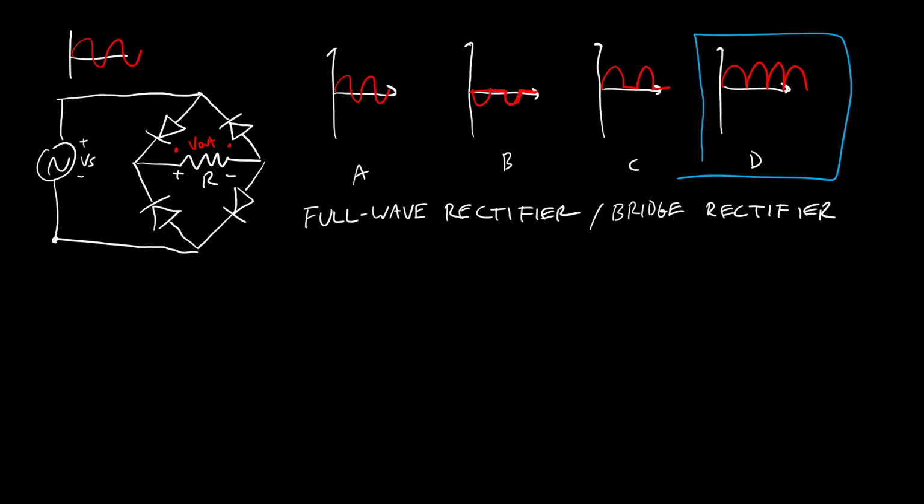Let's do something I should have defined earlier. I'm going to define ground there, just so we have a reference for 0 volts. And remember that with an AC voltage source, that means that's my 0 here. So this side of the source can swing either positive or negative relative to ground, depending on which part of this cycle I'm in. So when I have a positive voltage here, that means current's going to flow this way.